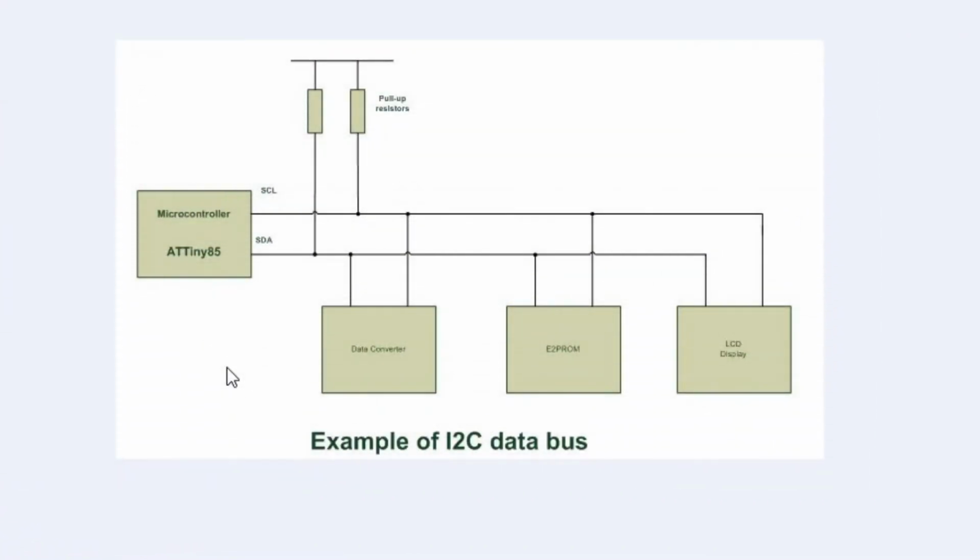One of the things you need to understand about the I2C bus is it is an open drain or open collector output. And so there is nothing connecting the internal part of the chip to these lines that pull the signal high. The lines are all pulled high by their pull-up resistors, hence called pull-up. The open drain setup may only pull the bus low or release it and let the resistor pull it high.